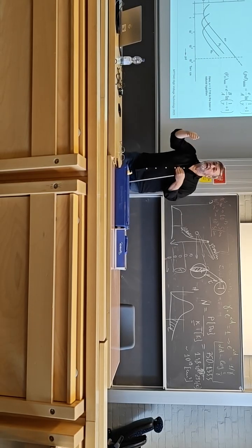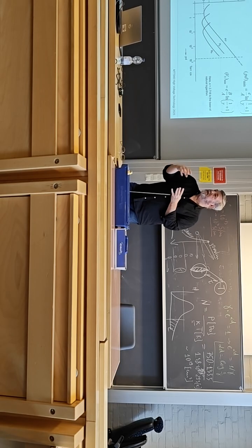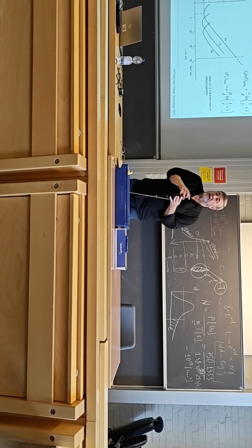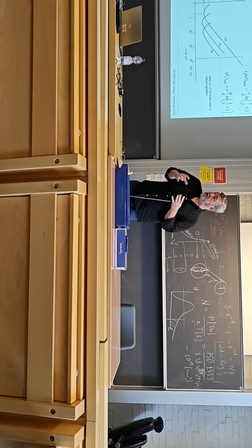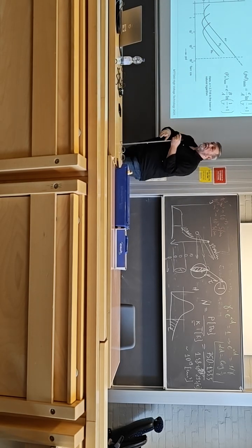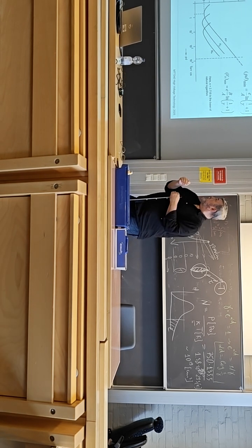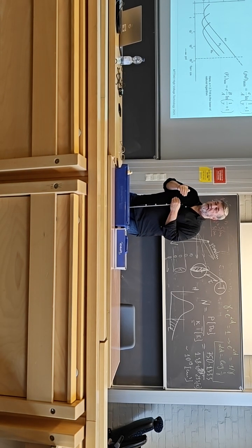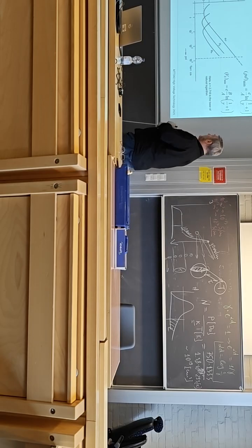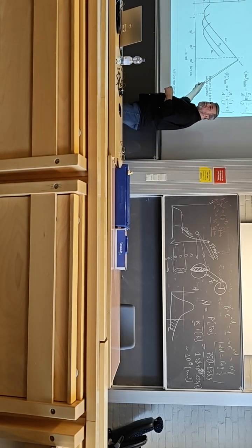If you go to the right, more and more neutrals appear, and the electron meets neutral molecules before it actually gains high enough energy. The higher you go in pressure, the more this happens, and then you actually need to apply a higher field to recover conditions for the ionization. That corresponds to the higher breakdown voltage.